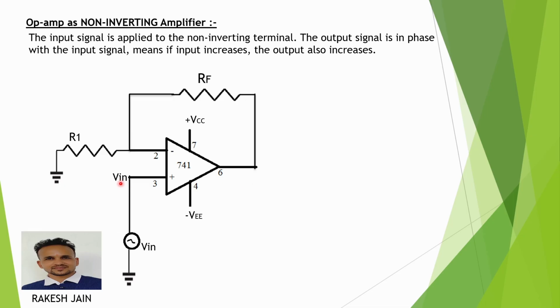Output voltage is V0, the input voltage is V in, that's why V plus is equal to V in, that is the non-inverting pin input. That's why due to the virtual ground concept, the inverting pin input is also V input, so as to maintain the gain very high, approximately infinite. Now RF and R1 form a simple potential divider. See, this one is a resistor R1 which is connected here because no current is drawn at the inverting pin. So this R1 is in series with RF, where the other point of RF is connected to V0.